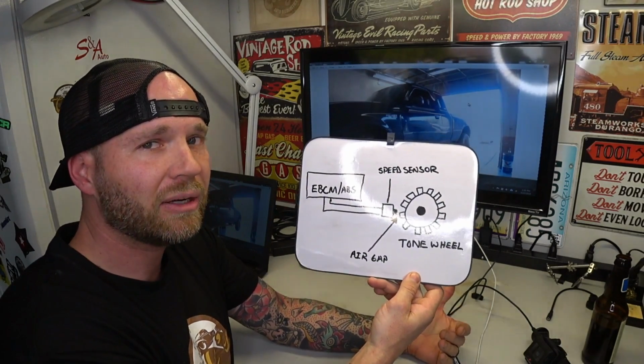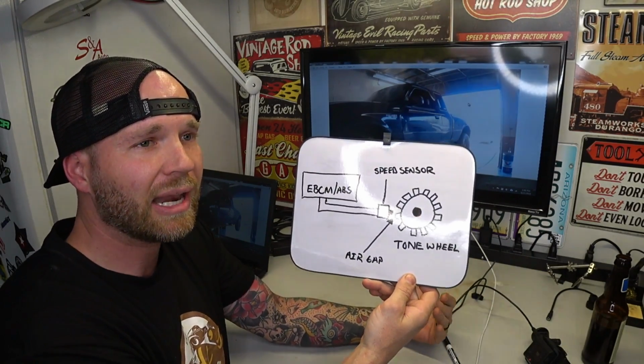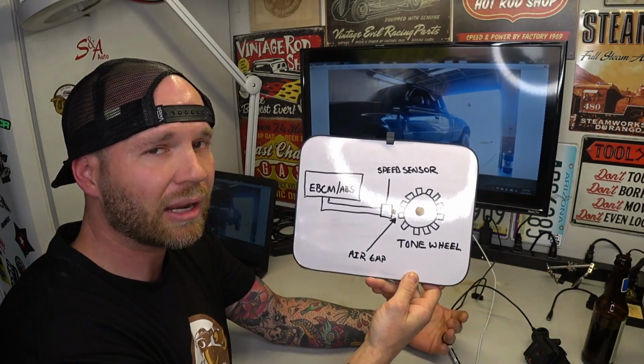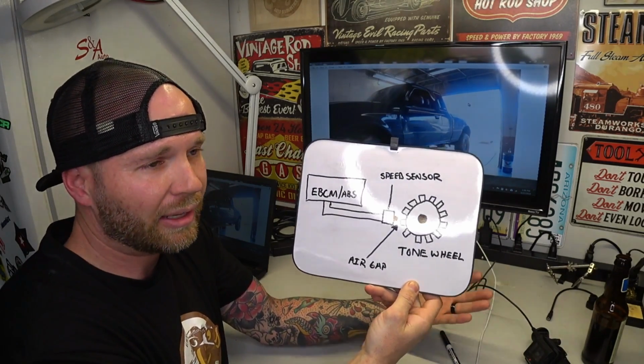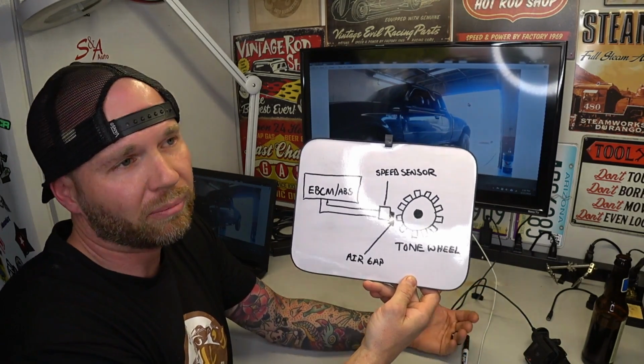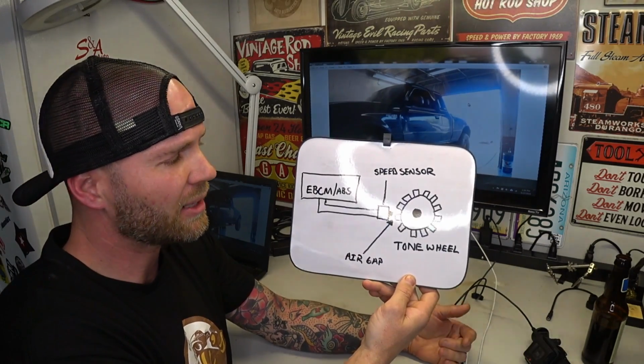But with a multimeter, it's going to take an average, and it's not going to show you everything like a lab scope. I grab my lab scope before I grab my multimeter, nine times out of ten.